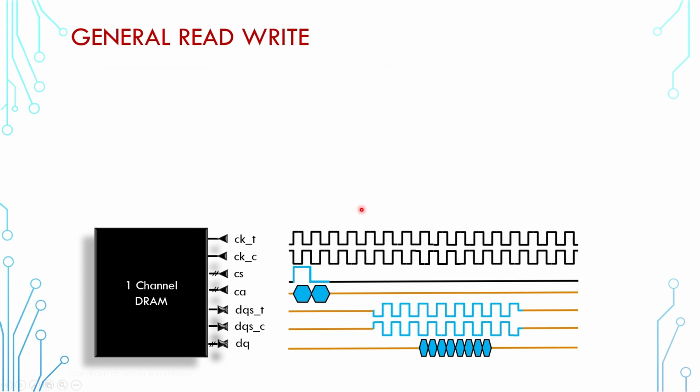Now let's pick some brains on this protocol. In this diagram, DQS has the same frequency as CK. This is true for DDR4, DDR5, and LPDDR4. But regardless of the technology, if DQS and CK have the same frequency, why don't we just use CK as the data clock? Why create extra signals, especially if it's expensive?